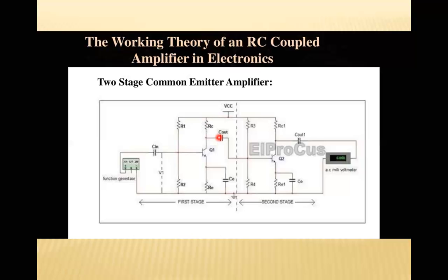So I can say that in the three-stage amplifier, the gain of the first and second will be reduced due to the loading effect of the next stage, because we are adding the next amplifier in a cascading manner. Because of that loading effect, the gain will be reduced. But if I take one more amplifier here, the third one, the output of the third amplifier will not be reduced because there won't be any shunting effect. That is the ultimate, final amplifier.